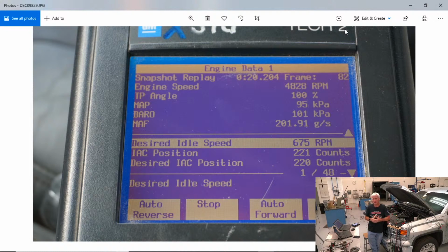We're not really expecting a naturally aspirated engine to be 100% volumetrically efficient. Usually 80% is about normal, and 75 is kind of low end. Some engines, like this LS engine right here, will do 95% VE if you test them. They're actually pretty good.